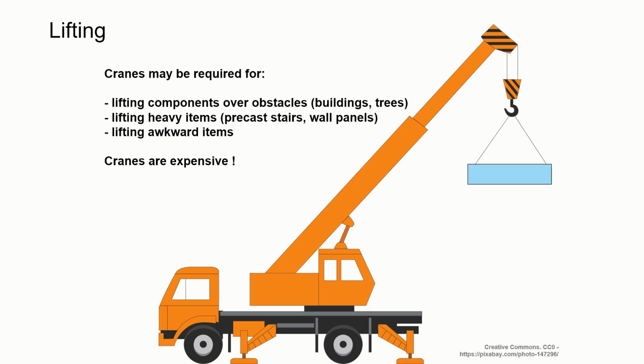Cranes are very expensive, so if you have to use them, it's best to plan out their use at the start. And that is right at the start as you're thinking about how the building is built and what technologies are used within that. How you might actually get those materials to site should be a consideration.